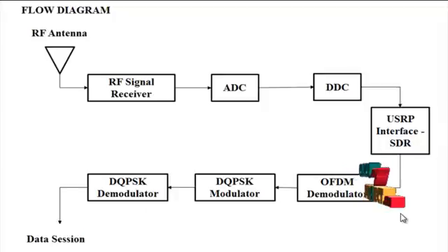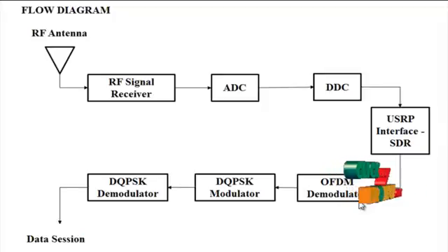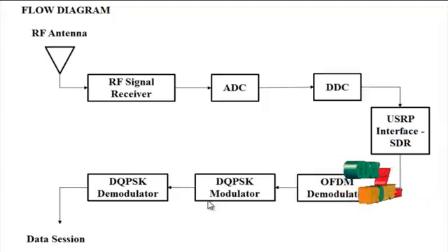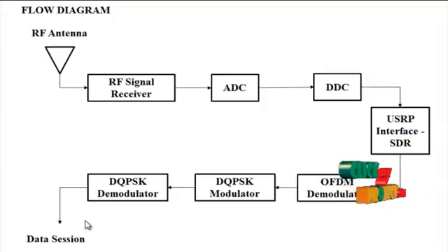In the OFDM receiver, initially the input signal is generated randomly, and the convolutional encoder converts the input signal into a binary stream. An adaptive modulation scheme is used for modulating the input signal. All the subcarriers in OFDM blocks are in comb-type pilot models. Some predefined subcarriers in each block serve as pilots. The Fourier transform breaks the signal into different frequency bins by multiplying the signal with a series of sinusoids. Finally, the data is retrieved from the DQPSK demodulator.